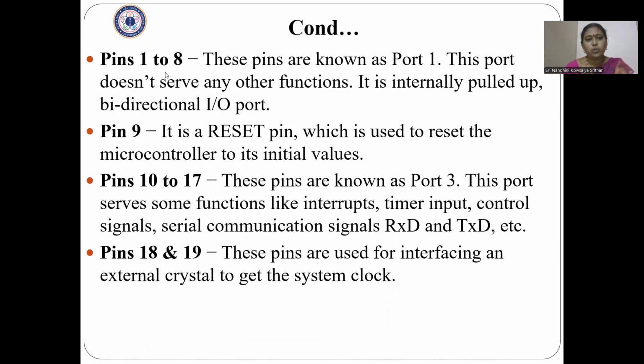So pin number 1 to 8, these pins are known as port 1. It is called port 1. This port does not serve any other functions. It is an internally pulled-up bidirectional input and output port. Then pin 9, it is known as the reset pin. It is used to reset the microcontroller to its initial values.